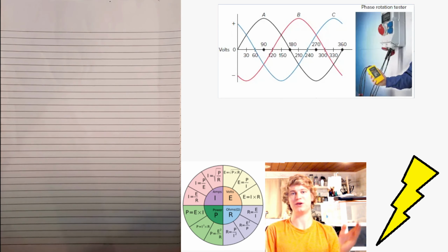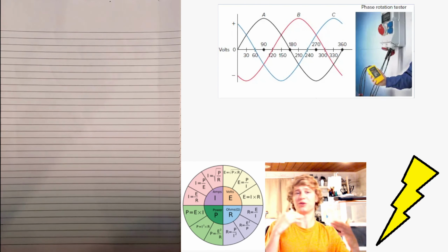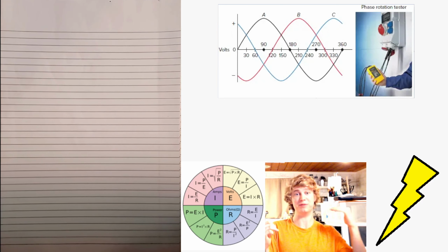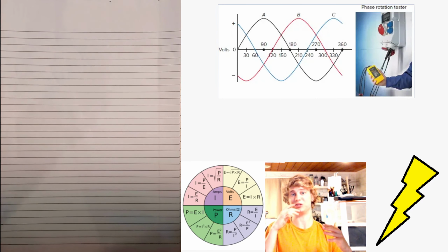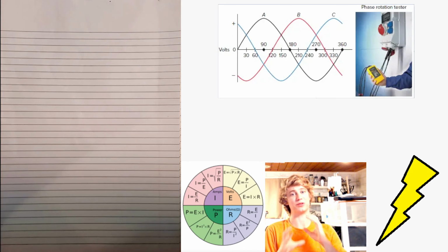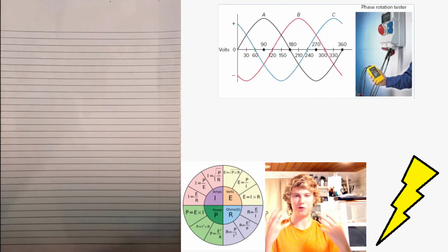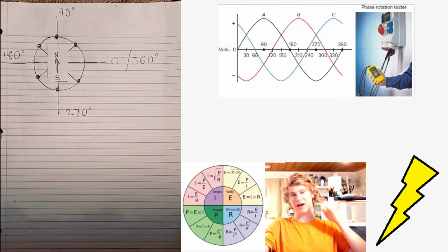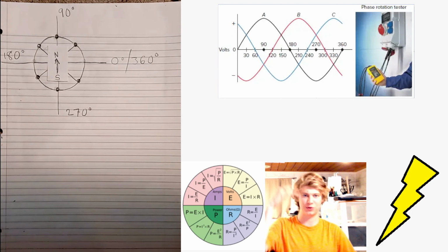There's never a point where any of them is at the 0 crossing when another one isn't at either the middle of its peak or somewhere between that and its actual peak. And the lowest point is where 2 of the phases are in the middle of where their peak would be. So you basically always have constantly a lot of power with a 3-phase system. Okay, so now if we still keep in mind the graph above, with the 3 different waveforms.